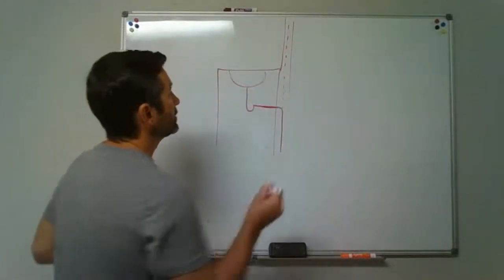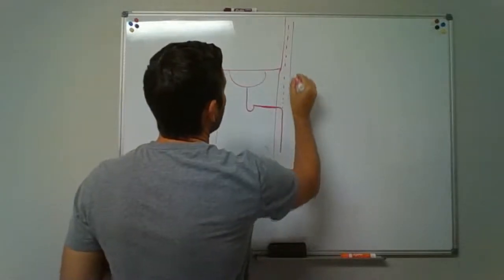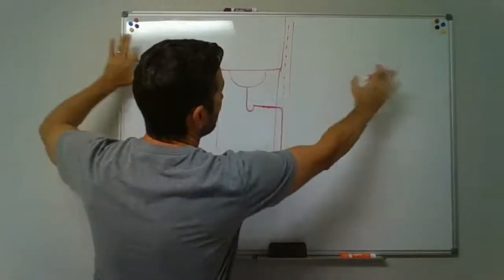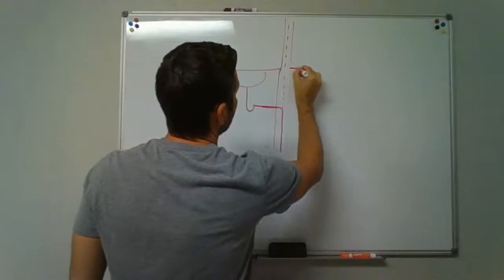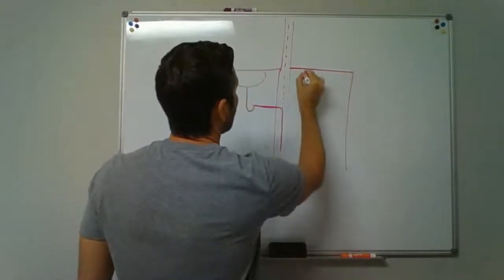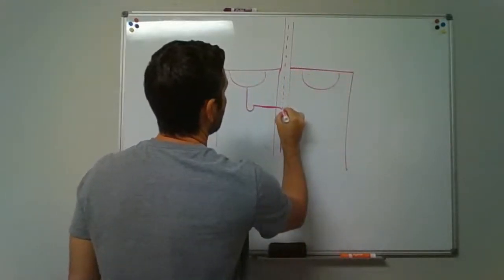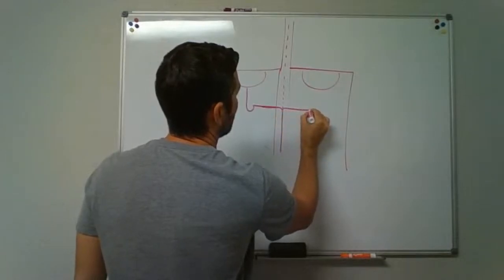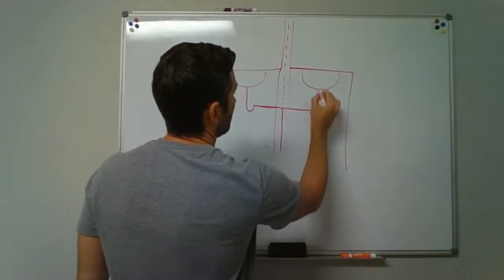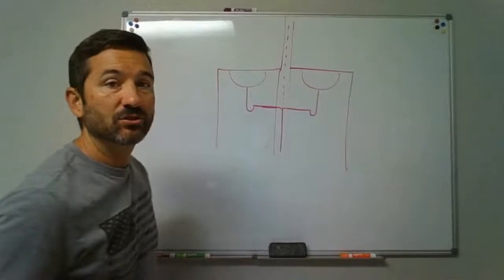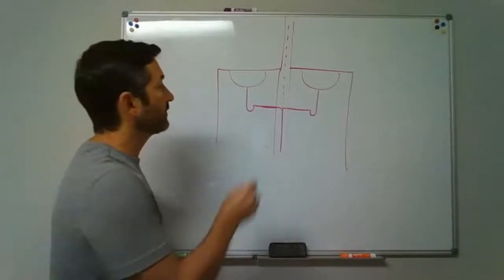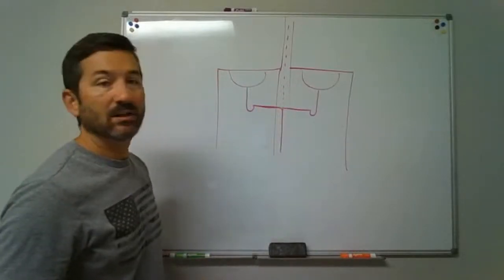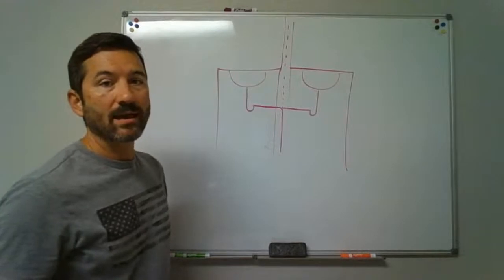But we are allowed to do something like this. Let's picture the wall as being behind this, and we've got a set of double lavatories. Now we have 2 trap fixtures with one vent in the middle, and we're going to call that a common vent.